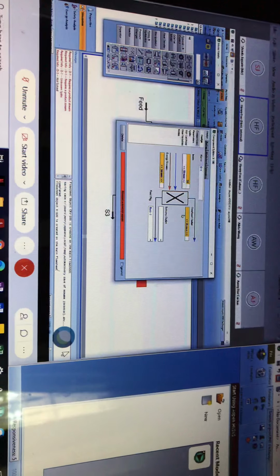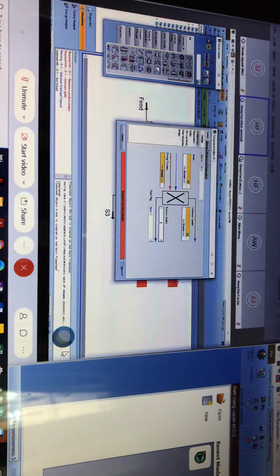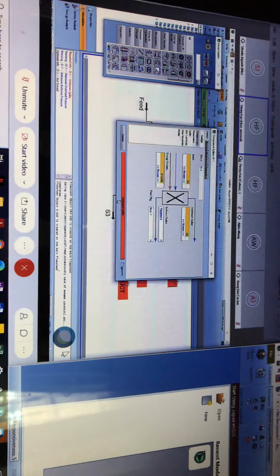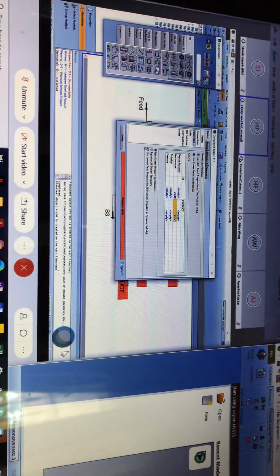The inlet should be S2. Overhead outlet is S4. You can type S4. And bottom outlet will be your product. So you type product. Energy stream is D duty. And the next step, they say you still have unknown split, but you can move on to the next step on parameters. Under parameters, you have to define the temperature for S4 and product. It's 25 degrees Celsius and 25 degrees Celsius. And select use lowest feed pressures for all products.